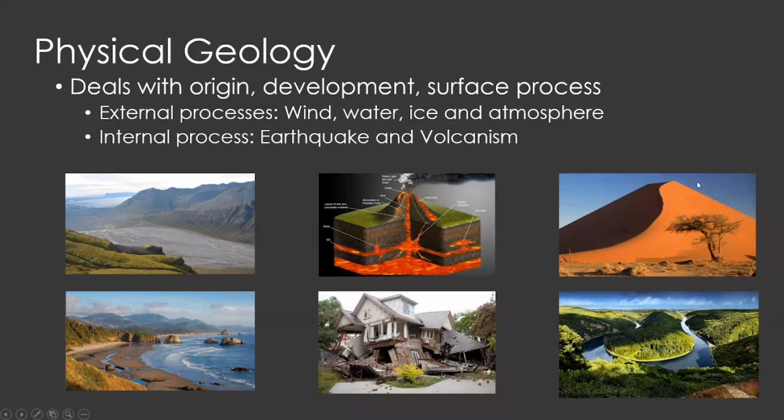Or in the case of a dune, this dune is still not a stabilized dune, and after some years this dune may move further ahead. There are chances that the plant or tree you are seeing here may be completely covered by the dune. If you are planning to construct a building in front of this dune, we should keep in mind that the dune may move further ahead. And this is the effect of an earthquake, which we see in this image.